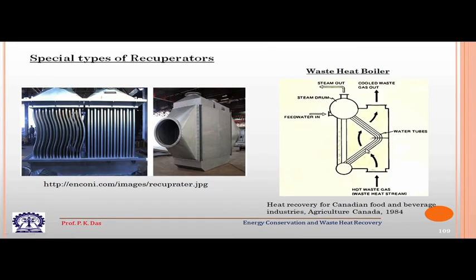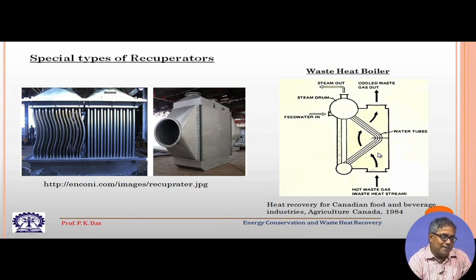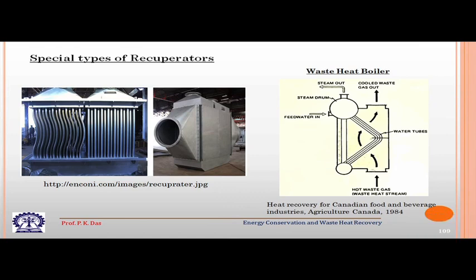For gas to gas waste heat recovery, the recuperator will not have fins on the hot gas side, because that is where fouling takes place, but it may have fins on the cold gas side. Economizers again have this tubular structure, whereas an air preheater in many cases can have a tubular structure, or it can have some sort of regenerative principle for extracting waste heat.